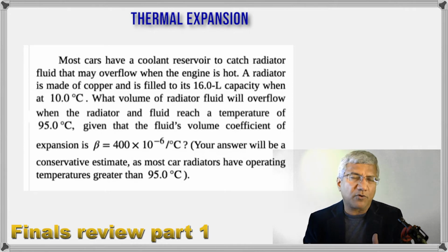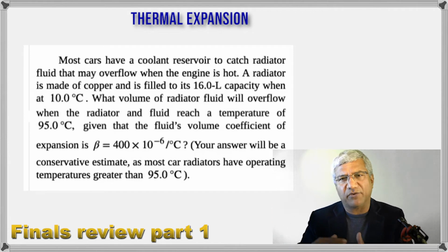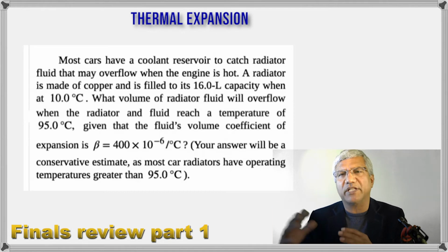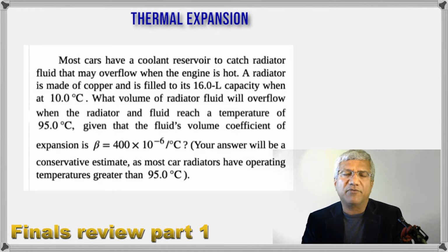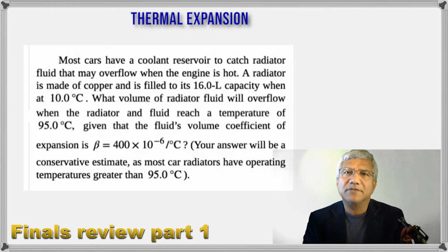So how do you find what volume will overflow? Surely the fluid expands more than the radiator does. So what we'll do is we'll find out how much the fluid expands, then we'll find out how much the radiator expands, and then we'll subtract how much the radiator expands from what the coolant expands. So that'll give us how much overflows.